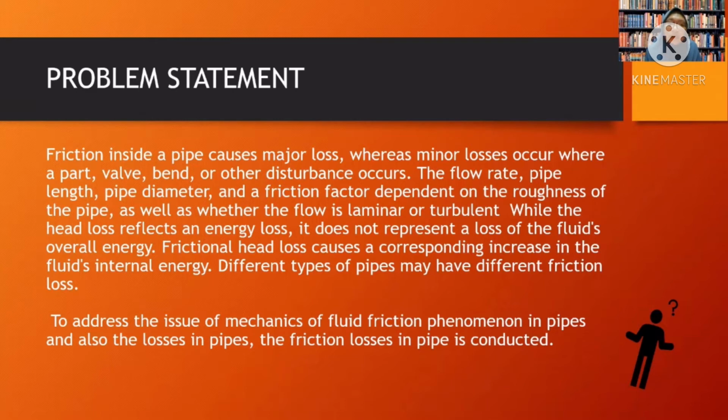While the head loss reflects an energy loss, it does not represent a loss of the fluid's overall energy. Frictional head loss causes a corresponding increase in the fluid's internal energy. Different types of pipe may have different friction loss. So, to address the issue of the mechanics of fluids, friction phenomenon in pipe, and also the losses in pipe, the friction losses in pipe experiment is conducted.